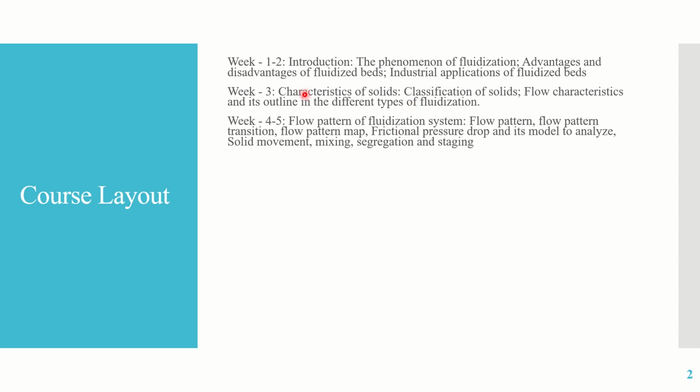So we all saw how different regimes of fluidization are observed depending on the inlet fluid velocity. The next topics, solid movement, mixing, segregation and staging, will be learned in further classes. They have not been covered by the lectures till now. Followed by that, we saw gas distribution systems and the various types, like porous plate distributor, perforated plate distributor, nozzles and tuyere type distributors, and how they influence industrial scale or small scale setups. We also saw how to design those distributors and how the distributor affects the pressure drop of the bed, and what the disadvantages are of having a higher pressure drop in terms of pumping cost, etc. All these were covered in those classes.